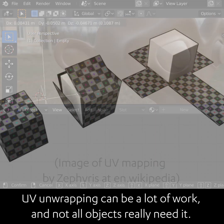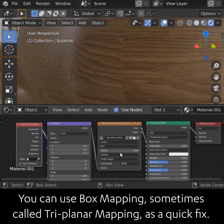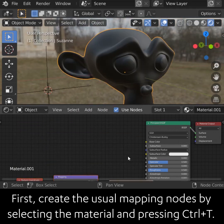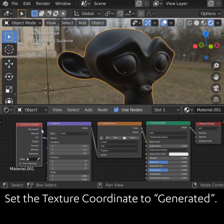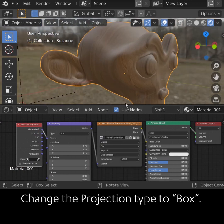UV unwrapping can be a lot of work and not all objects really need it. You can use box mapping, sometimes called triplanar mapping, as a quick fix. First, create the usual mapping nodes by selecting the material and pressing Ctrl T. Set the texture coordinate to generated. Choose a texture. Change the projection type to box.